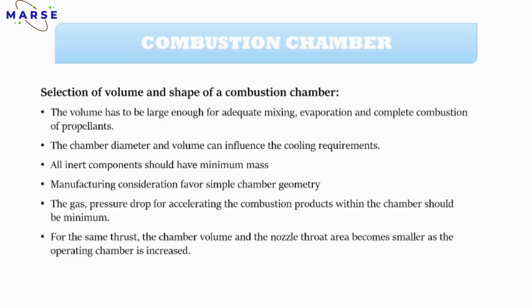The volume has to be large enough for adequate mixing. For example, in the previous slide we discussed the small volume, big volume, larger length, smaller length. These parameters are very influential. If the volume is not large enough, then the mixing process, the evaporation process, or the combustion process will not be carried out perfectly in that particular chamber. So it should be large enough for adequate mixing, evaporation and complete combustion of any particular propellants.